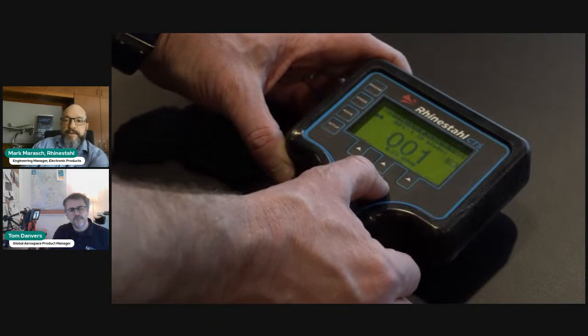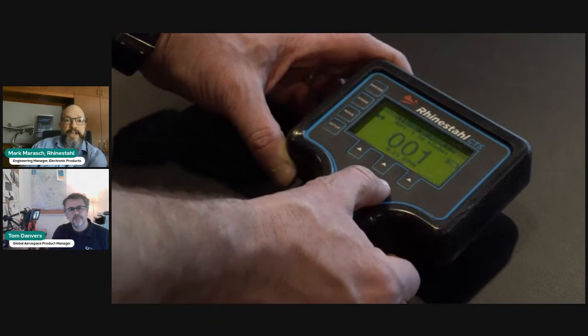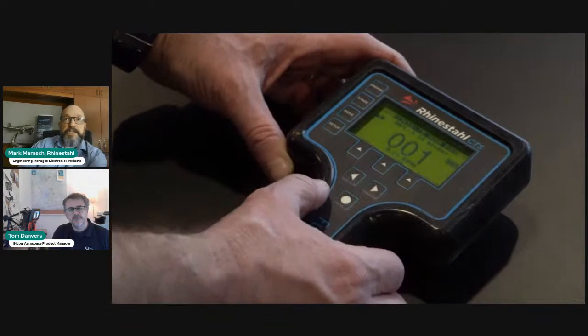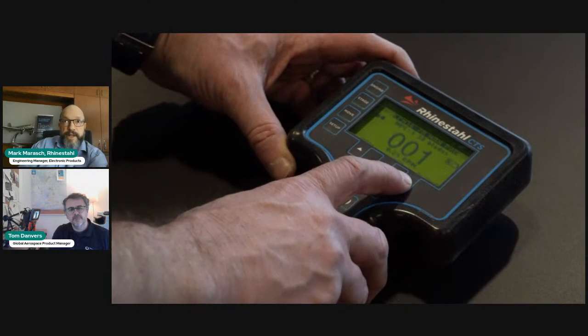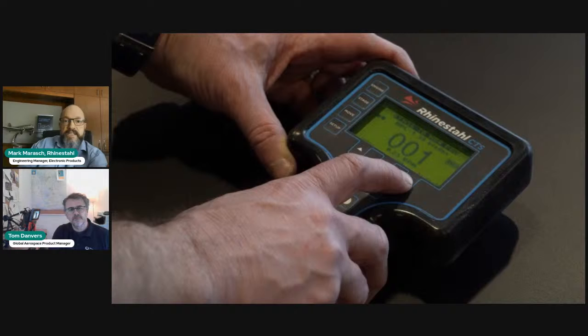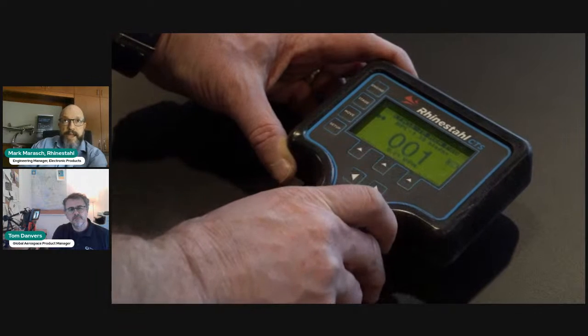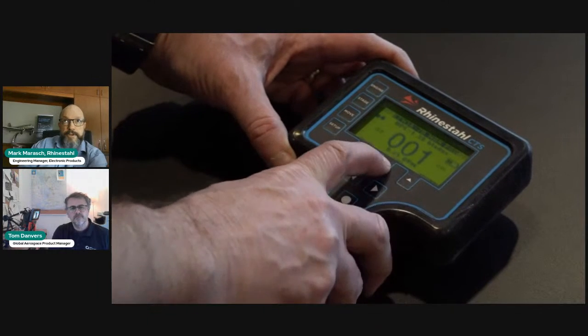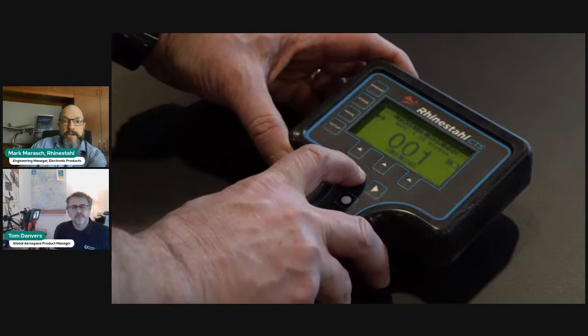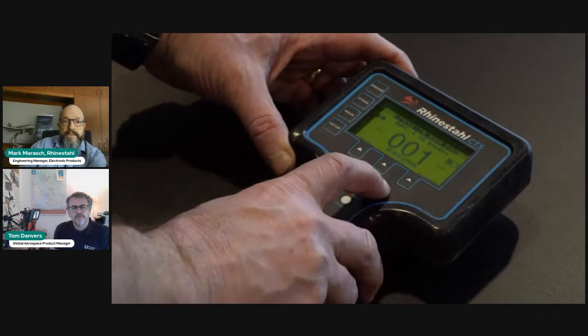and use the arrow keys to select the profile of the engine and interface we're using. For an engine that can be turned in both directions, we select backlash. Then we select speed and slow the system down, because it works better if you do this slowly. So we'll select the speed, turn it down, and we go back to backlash.